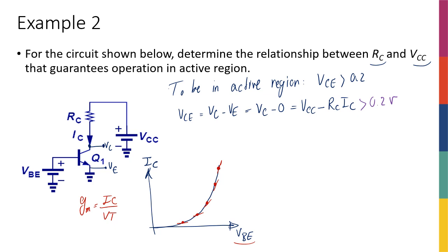And remember that I said there's a trade-off. Why don't I just increase my VBE to infinity and enjoy my really high gain of the transistor? Well, because that means the collector current is going to increase, therefore I'm going to have more and more power consumption, right? There's actually another reason I don't want to increase VBE, another reason against increasing GM without any limitations, and that's really here.